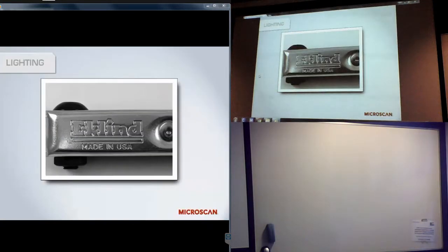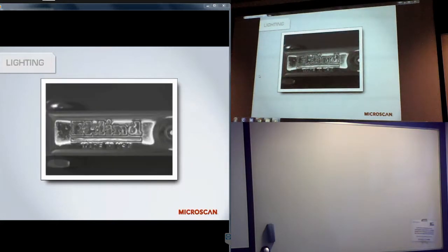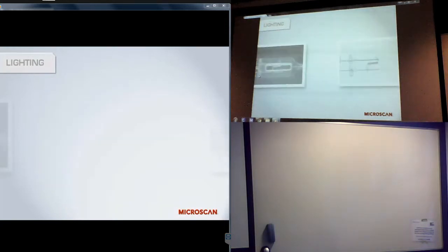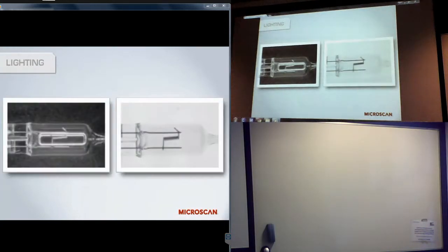The type and position of a light should be carefully selected to maximize contrast of the features you plan to inspect and minimize contrast of everything else. This is like an electrical engineer setting up a system to give a high signal-to-noise ratio. You're trying to make the pieces you need to see, or need to measure, very clear, and you want all the other items in the image as invisible as possible. To give you an idea of how you might do this, let's look at some examples.